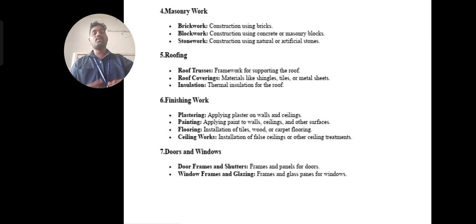So anybody who wants to identify should see how many types of doors there are in the plan, and then identify the number of doors in the plan, so that we know the cost of the door and the cost of the window individually. For example, the cost of a door may be 1 lakh to 2 lakh, based on the material, maybe teak.